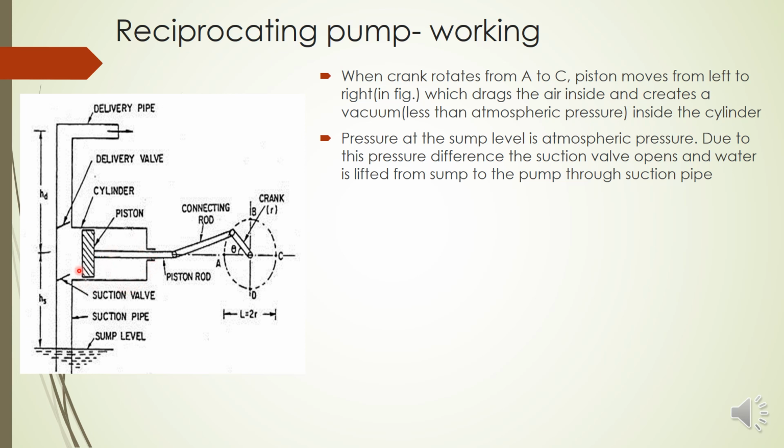So that is what is happening in the first phase. The piston is moving, it drags air, creates vacuum. The pressure is less than atmospheric pressure, but at the sump we have more pressure, it is atmospheric pressure. So obviously the water will lift and reach the cylinder.